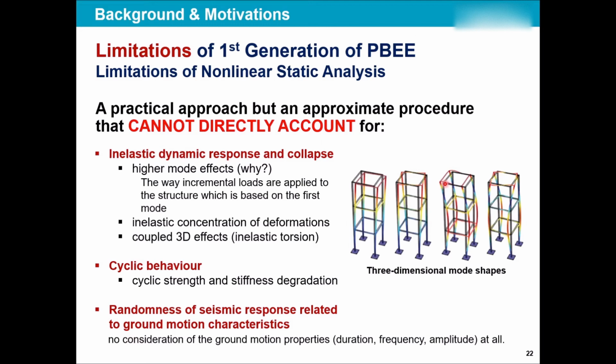But earthquake, as we know, is not as simplified as that. It strikes your building from every single angle, and even moves your building up and down. So that's a limitation of the static pushover analysis, which we didn't consider. On the other side, the pushover analysis cannot capture very localized, concentrated deformation, like local buckling. All of these are kind of ignored in this analysis.